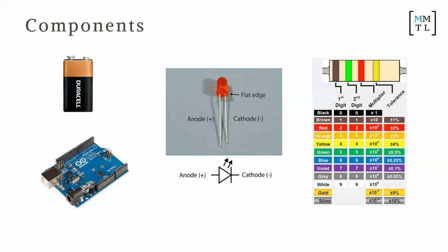We'll be using generally the 5% or the 10% tolerances. In your pack, it is actually marked with whether it's 10K, 1K, or 330 ohms. But practice looking and seeing if you can find the 330 based on the color alone, because this is what you actually have to do in real life. See if you can find 330 ohms in particular.